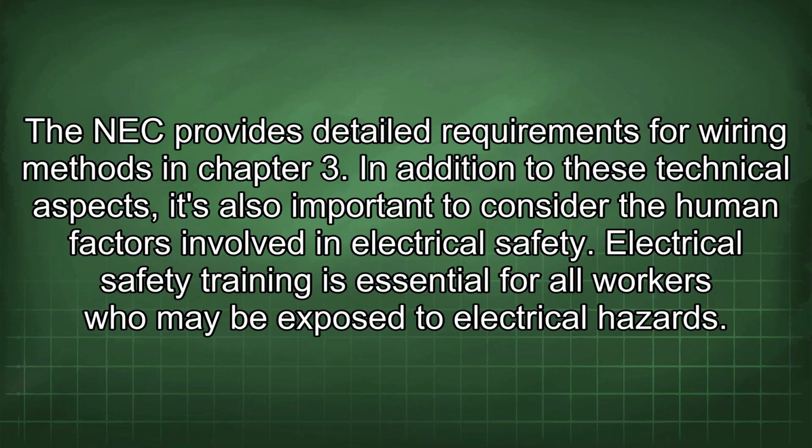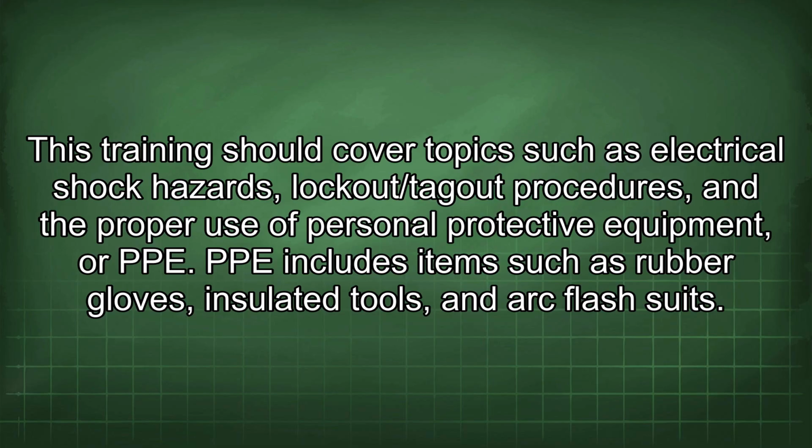In addition to these technical aspects, it's also important to consider the human factors involved in electrical safety. Electrical safety training is essential for all workers who may be exposed to electrical hazards. This training should cover topics such as electrical shock hazards, lockout/tagout procedures, and the proper use of personal protective equipment, or PPE. PPE includes items such as rubber gloves, insulated tools, and arc flash suits.